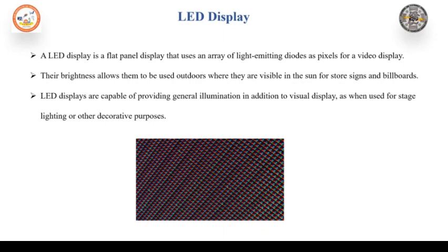Typically, these electrons give up energy in the form of heat and light. In silicon and germanium diodes, most of the electrons give up their energy in the form of heat. However, with GaAs, GaAsP and GaP semiconductors, the electrons give up their energy by emitting photons. If the semiconductor is translucent, the light will be emitted and the junction becomes a source of light, that is, a light emitting diode. LEDs emit no light when reverse biased. In fact, operating LEDs in reverse bias mode will quickly destroy them.